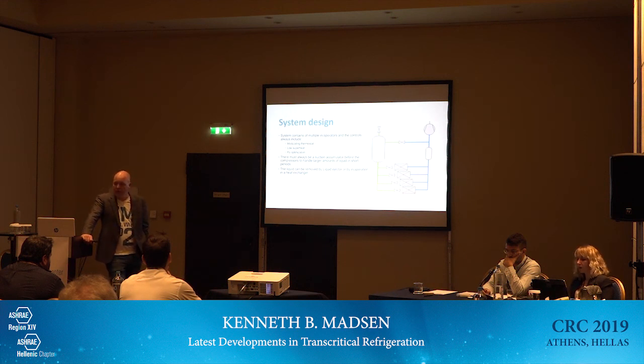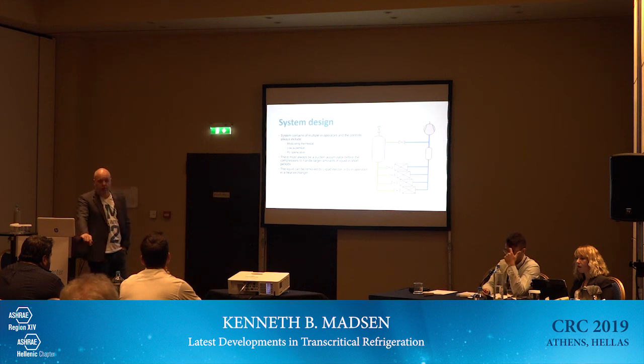That basically means that some of the evaporators are running on superheat control, but the others, the ones that are not so loaded, are running with temperature as set point for the valve. And then to increase the suction pressure, we also need to run pressure optimization. So that's basically the 3 control issues that we need to use.